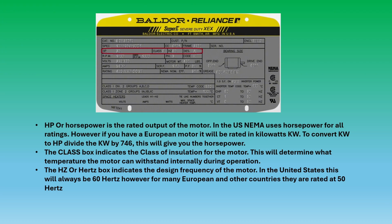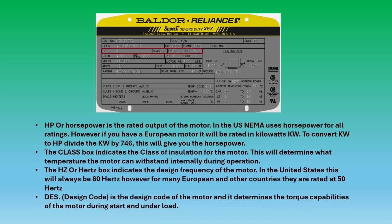The Hertz box indicates the design frequency of the motor. In the United States, and several countries, this will always be 60 Hertz. However, for many European and other countries as well, they are rated at 50 Hertz. DES or the design code. This is the design code of the motor and it determines the torque capabilities of the motor during start and under load.